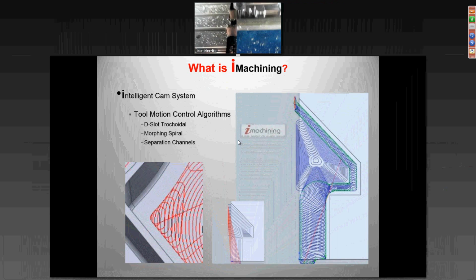It's a necessary evil, and we have to do it sometimes, but the more we can keep the tool in contact with the material, the more chips we're bringing off of it, okay? And in order to get from some abstract shape like this down to a collapse center, we can't keep it at a solid single cutting angle. We have to allow it to morph between a minimum and a maximum in order for it to be able to stage through these areas.